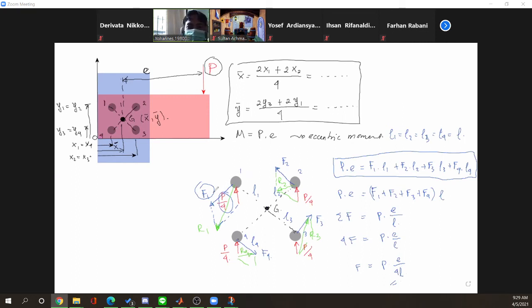Okay, so by observing this parallelogram of force, we know that the critical part means that the biggest resultant can be found in here and here. Okay, so here we have to calculate the resultant at this rivet. It will be the same with this one.